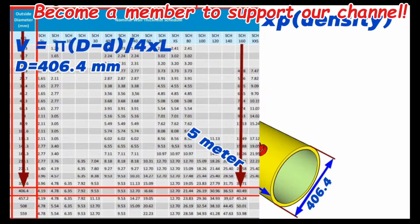Then, the inside diameter will equal the outside diameter 406.4 minus 2 times wall thickness 40.49. Using the calculator, we find that 406.4 minus 2 times 40.49 is approximately 325.